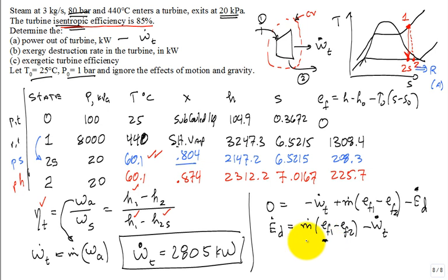You can read this equation. This is the change in the flow exergy of the fluid stream through the turbine from inlet to outlet. It comes in high, goes out low. Multiplied by m dot, that's a rate at which the fluid stream provided an exergetic flow into the turbine. Where did it go? We want as much of that to go into the shaft power as possible and go out that way. What happened to the rest? It was destroyed.